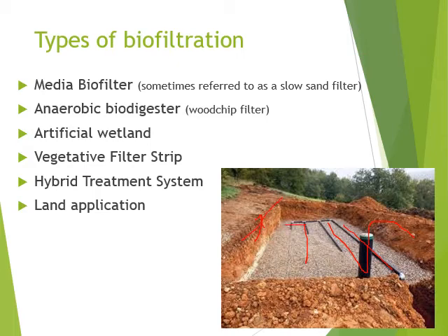There's an anaerobic environment where the nutrients are consumed, and the biofilm on the gravel consumes any pathogens like E. coli and whatnot. The water that eventually seeps out of this into the ground is treated. Now, we're not reusing that necessarily, but think about it. A lot of people that have a septic bed have well water. So they do work, and it is a sort of biofiltration, obviously.